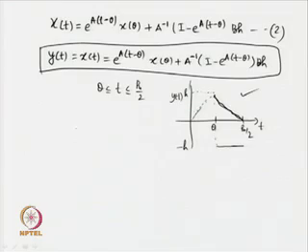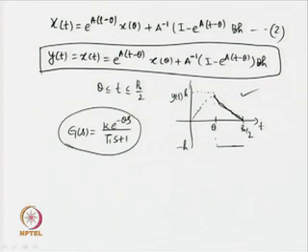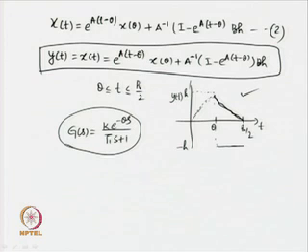What I mean by that is, since the system is now G(s) = k e^(-θs)/(T1 s + 1), when the system is subjected to a relay test, then the system produces a typical output of this form, and we have been able to derive analytical expressions for the output of the system.